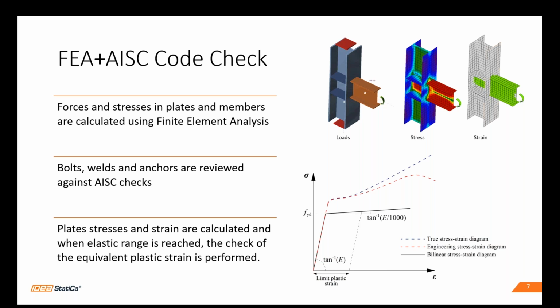One thing to note, we do look at the stresses and strains. Once we get past the elastic range, there is a small amount of plastic strain that is allowed within the software. That's obviously from our European background. Eurocode allows a 5% plastic strain to be used. What we've been doing is verifying those analysis results and confirming that the 5% strain limit actually correlates pretty well with the code equations.